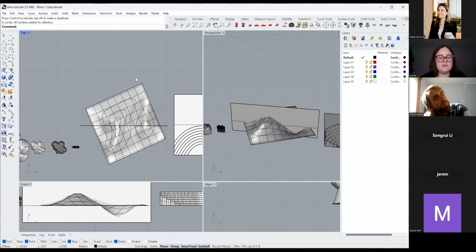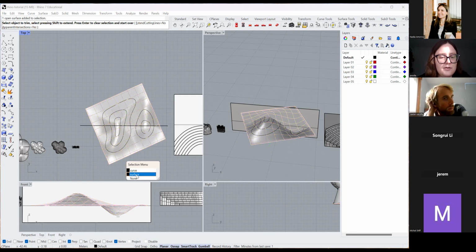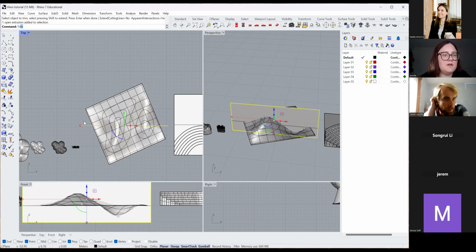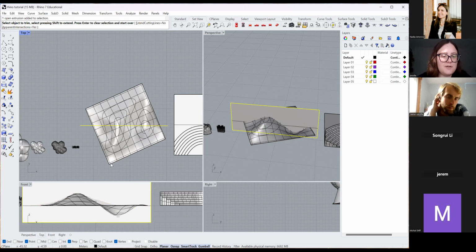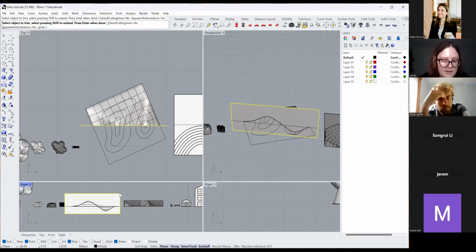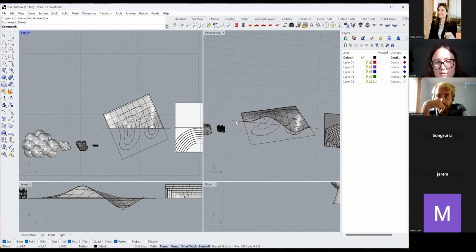And then what you do is you just trim, and then you trim this. Objective trim, and that would be this surface. So now you can see that I have cut away what's in front of this trim line, and that's your section line.